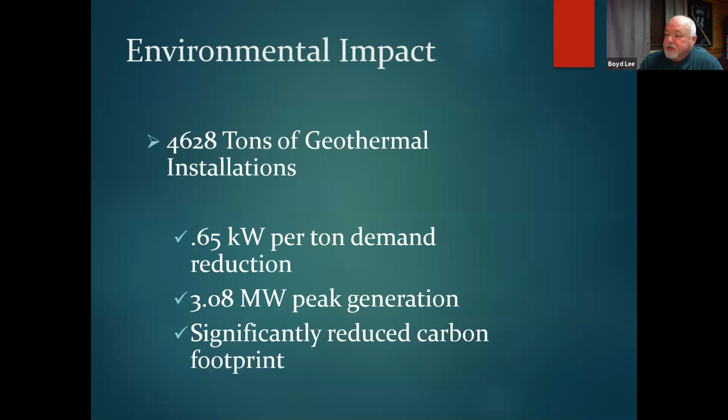4,628 total tons. 0.65 kW per ton demand reduction. That's 3.08 megawatts that we've reduced at peak. That is worth hundreds of thousands of dollars every single year. And we've significantly reduced our carbon footprint for the folks that are concerned about carbon footprints. So it answers every single question that's out there.